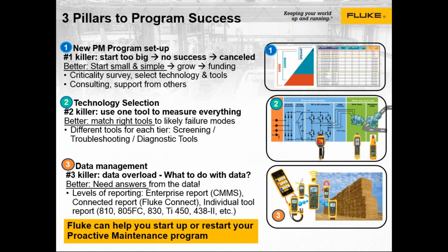Since we all have limited resources and we're having to do more with less, the first exercise is to find out which machines are critical. The second step is that this determines which machines you go after, but also how often you want to screen this machine, and how often you want to diagnose this machine. So just start simple and use Excel spreadsheets.